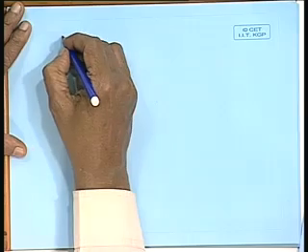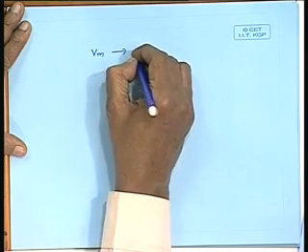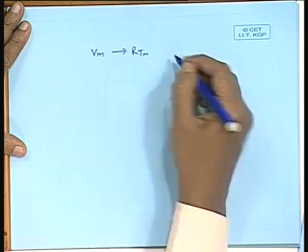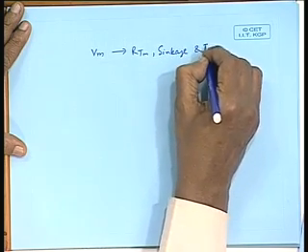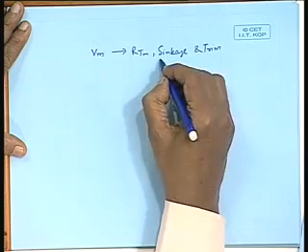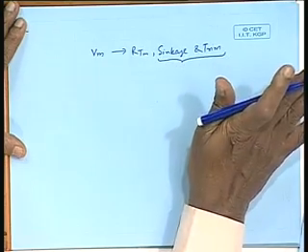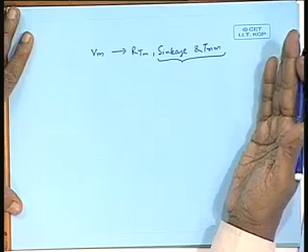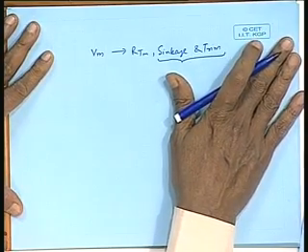We are measuring VM, RTM, sinkage and trim. For normal conventional merchant ships, we will ignore this. This is important for other types of vessels, but not for conventional displacement type merchant ships moving below 0.3 Froude number. What else do we know?